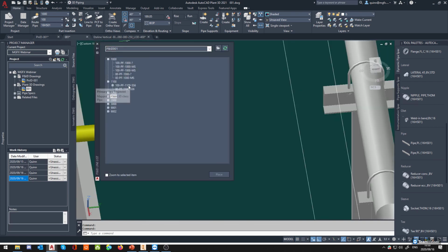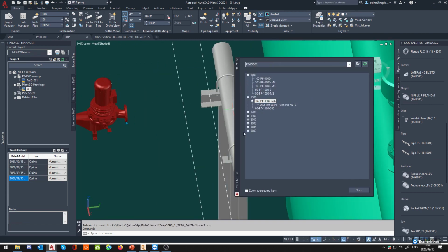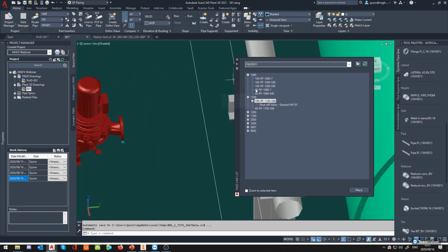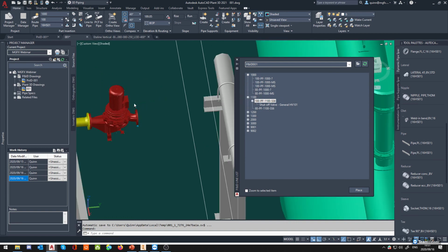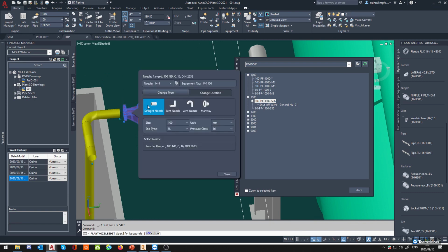What this then means is that I can use this line list, expand it and say, oh, okay, well, what do I have in here? It's not actually giving it to me right now. Okay, well, it is kind of, it's not giving me the whole thing. What I can also do is generate selector lines as well. So what I can do is I can start routing a line. Firstly, I need to fix these nozzles. I'm going to change the nozzles to 80.